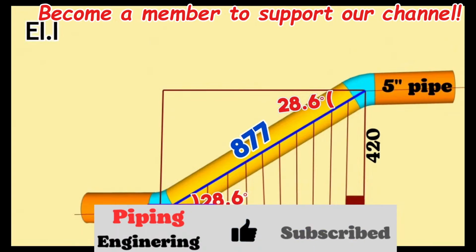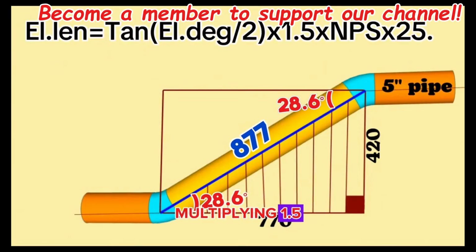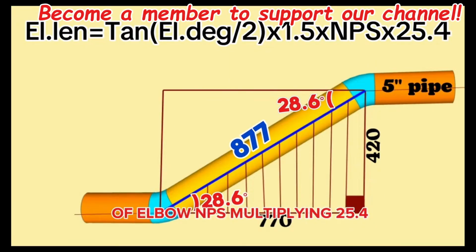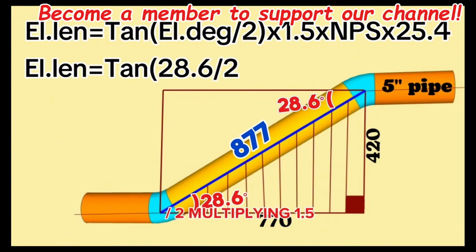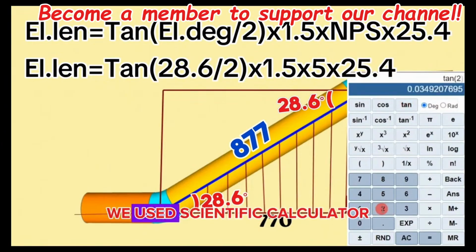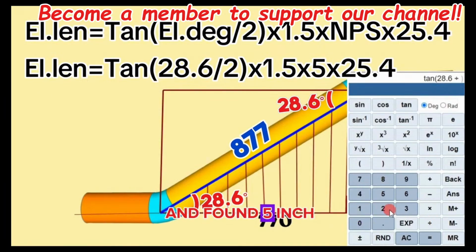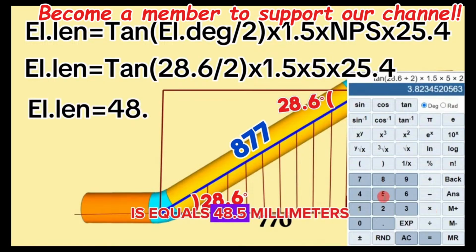Elbow length is equal to tangent of elbow degree divided by 2, multiplying 1.5, multiplying nominal pipe size of elbow NPS, multiplying 25.4. For this 5-inch 28.6 degree butt weld elbow, length equals tangent 28.6 divided by 2, multiplying 1.5, multiplying 5, multiplying 25.4. We used a scientific calculator and found the 5-inch 28.6 degree butt weld elbow's length is equal to 48.5 millimeters.